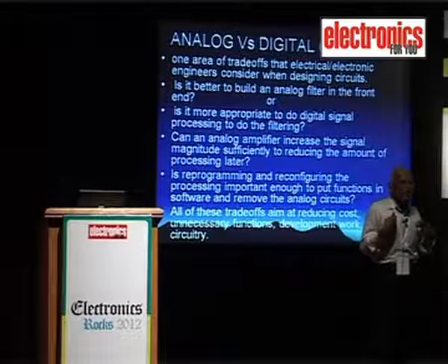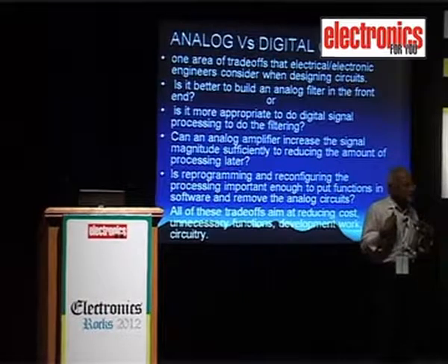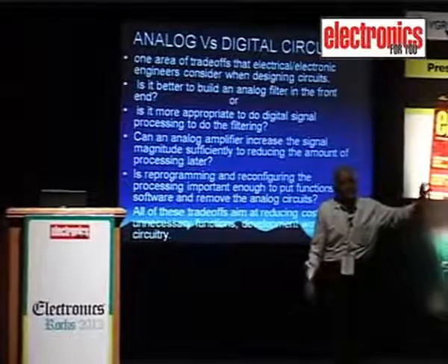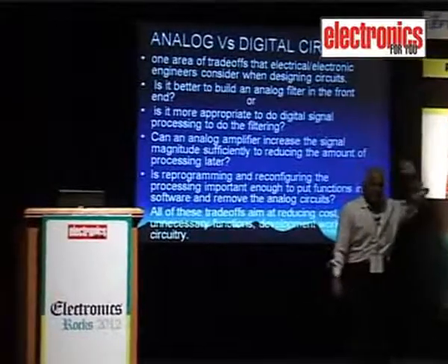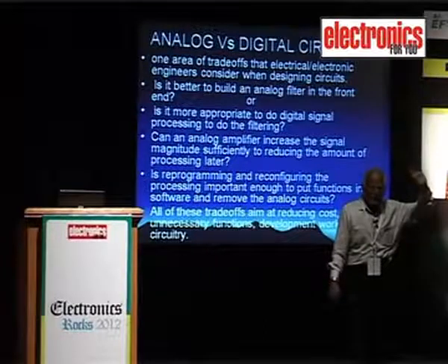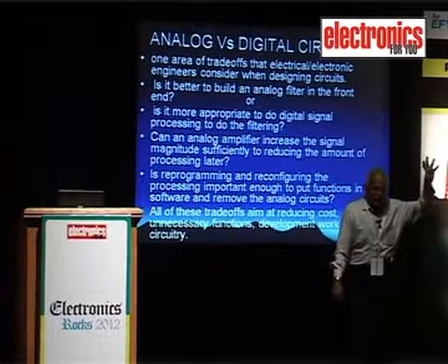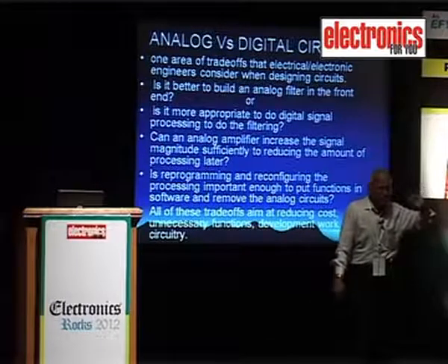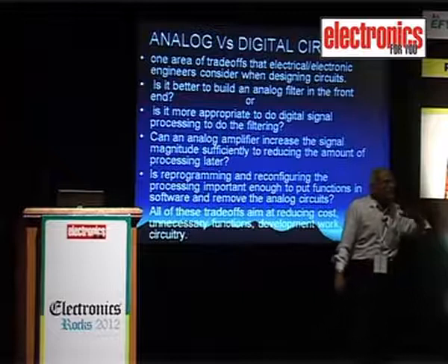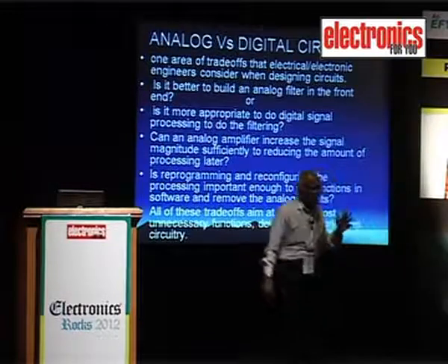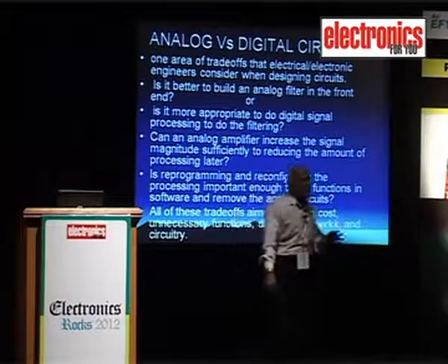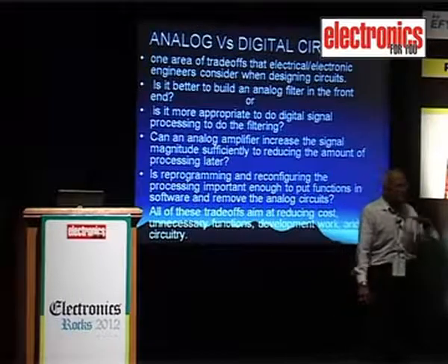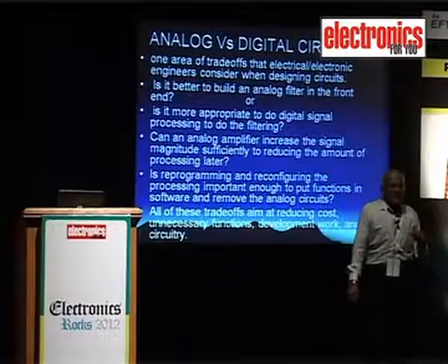monitoring high voltages, power of 400 kV stations. They said it is 48 volts plus minus 10%. So 48 volts plus minus 10% means what? 48 plus 4.8 is around 52, 53. Minus is what? 44. But if you really take a battery, a 24 cell battery, it's normally charged to not 48 volts. They say 24 into 2 is 48. But actually it goes to 51.2 volts.